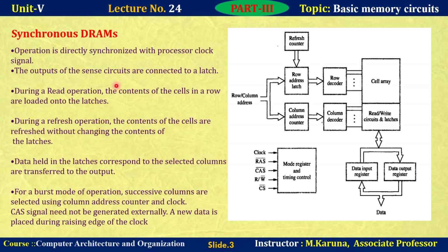So the outputs of the sense circuits are connected to the latches during a read operation. Then the processor issues the read signal, an active high signal, to the mode register and timing control circuit. During a read operation, the contents of cells in a row are loaded onto the latches. During a refresh operation, the contents of the cells are refreshed without changing the contents of the latches.